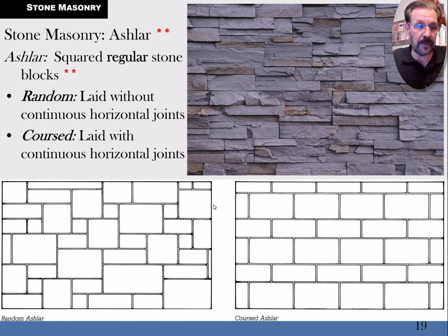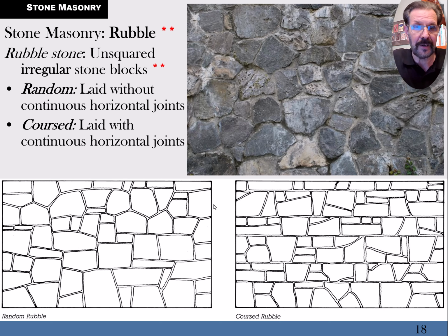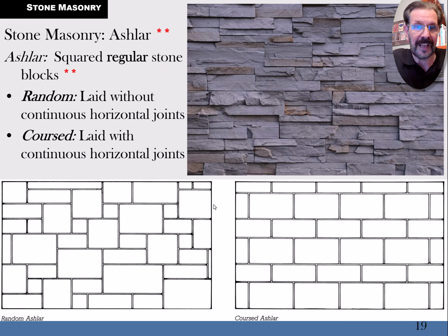These kind of terms can show up on the specifications of a drawing that you're bidding a job on. If you don't know these terms, your eyes will glaze over and you'll miss it and you'll misunderstand. The labor will be higher in the rubble, whereas the ashlar will be higher cost in the materials. And I'm not sure that they balance out or not. But these are important